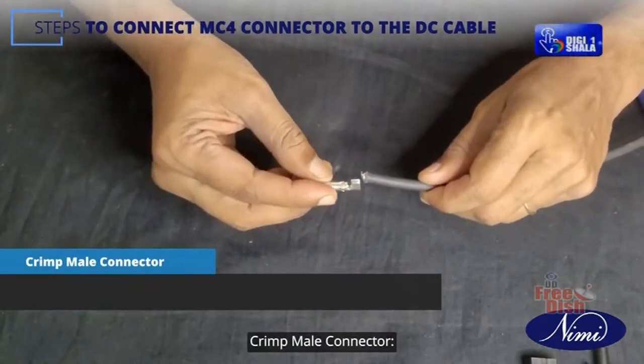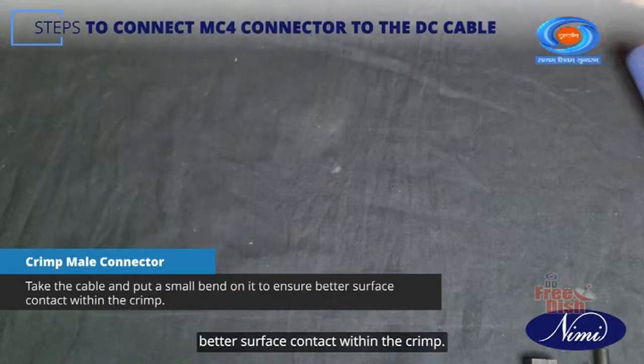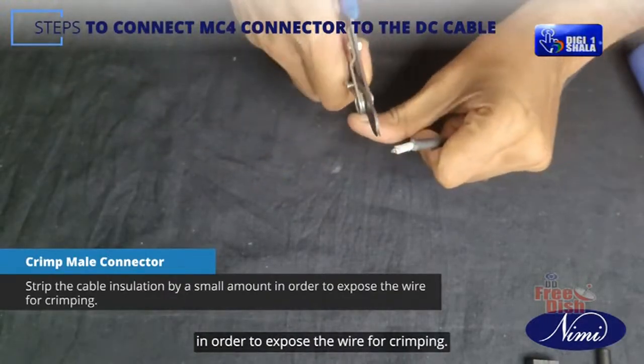Crimp male connector. Take the cable and put a small bend on it to ensure better surface contact within the crimp. Strip the cable insulation by a small amount in order to expose the wire for crimping.